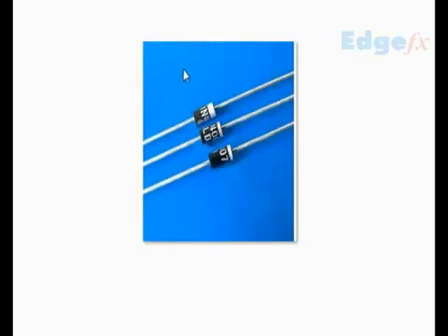And we know in electronics we have to derate their application in terms of the current and the voltage also. For example, if this is a 1200 volt PIV, we can use it maximum till about, say, 500-600 volts as far as the supply voltage is concerned, and a current rating of about 500 milliamperes to be on the safe side.